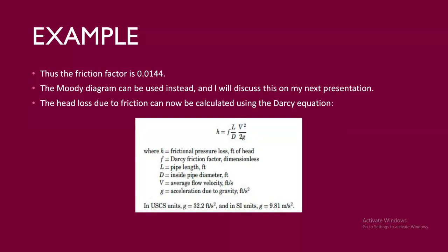You see, it's a bit tedious in the turbulent flow regime to calculate the friction factor, compared to my previous presentation where for the laminar flow regime, it was straightforward. So the Moody diagram can be used instead, and I will discuss this in my next presentation. So the head loss due to friction can now be calculated using Darcy's equation.